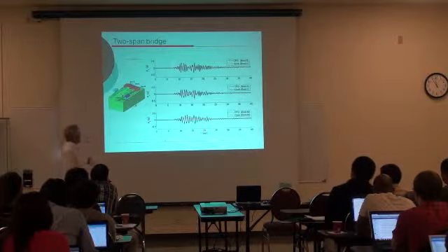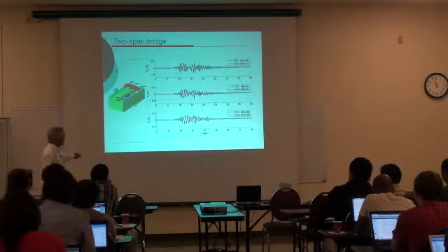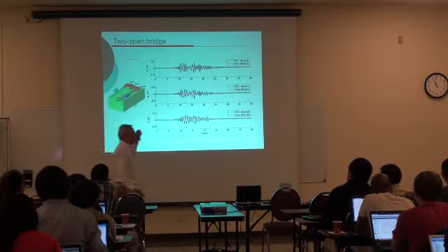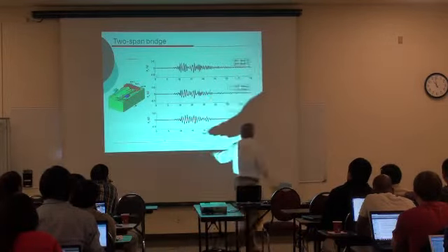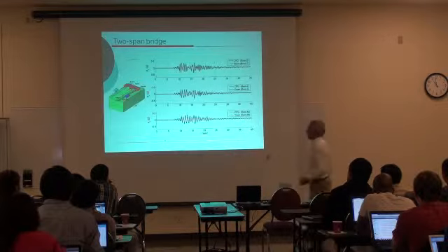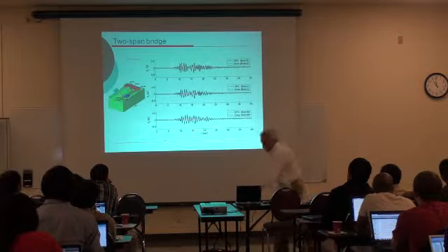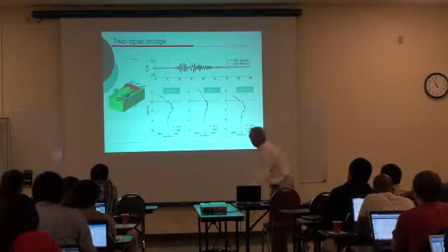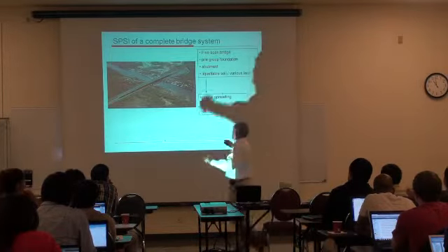If you're looking at the response at the proximity, at the interface here between the pile and the soil, this model is going to be bad. But if you're just looking at accelerations at the top of the bridge bent, the simpler models may be good enough. And again, you have here the bending moments. Let's look at this other example.